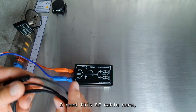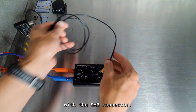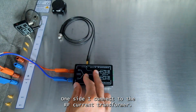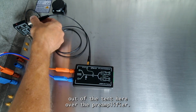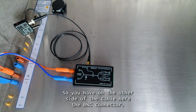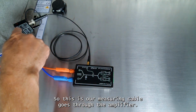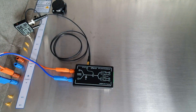I need this RF cable here with the SMB connector. One side I connect to the RF current transformer. And the measured signal goes out of the tent over the preamplifier. So on the other side of the cable you have the BNC connector. This is our measuring cable, goes through the amplifier and then out of the box.